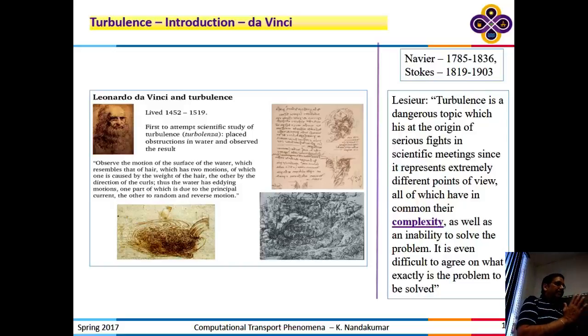It contains all the physics in laminar flow and in turbulent flow. But we typically use it in COMSOL only for solving laminar flow problems, like the Taylor-Couette problem that you're solving. As the flow becomes turbulent, even though the physics is embedded in that, the scales in which the flows develop are very broad, both in temporal and spatial. So we cannot directly solve that. That's called DNS for turbulence, direct numerical simulation of the Navier-Stokes equation. And we cannot do that simply because of lack of computing power.